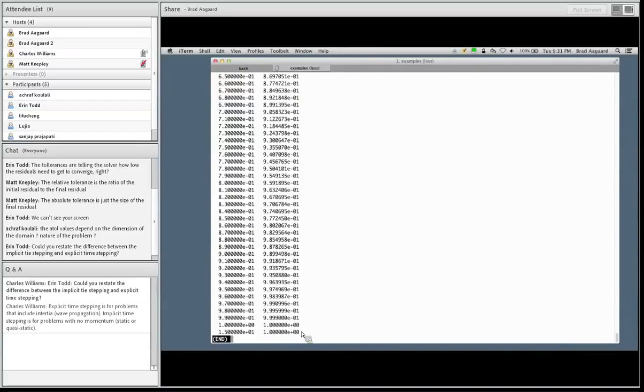And I used a normalized amplitude here from 0 to 1. I could have done 0 to 2, but then that gets multiplied by whatever value I had for my amplitude internally in those settings. And so it makes much more sense to use a normalized amplitude in my time history file of 0 to 1. So I just control the amplitude within my .cfg file.